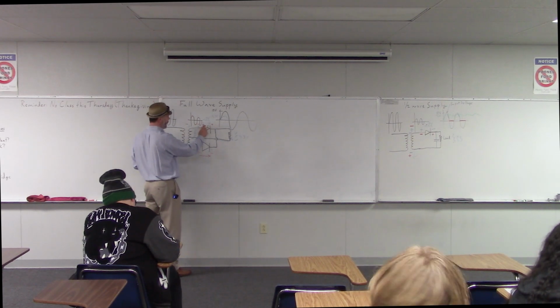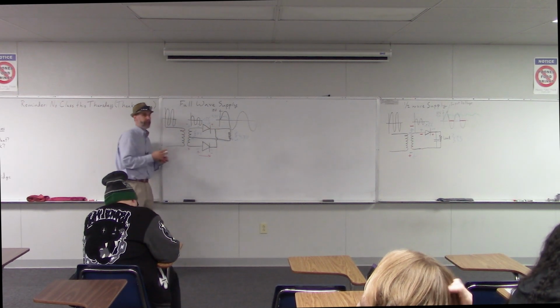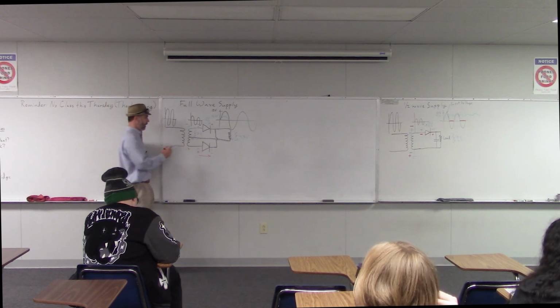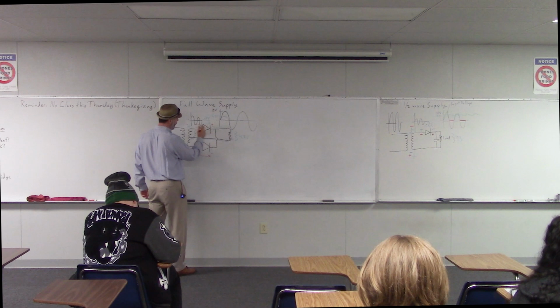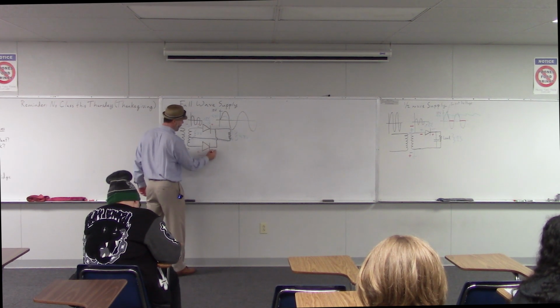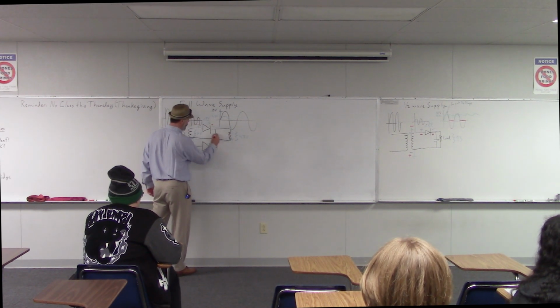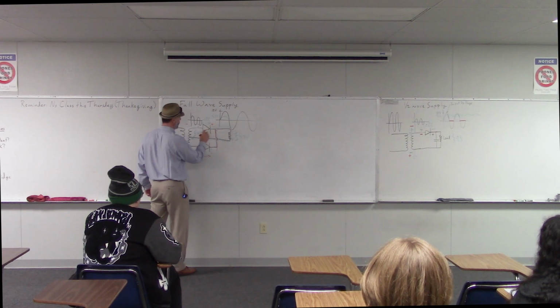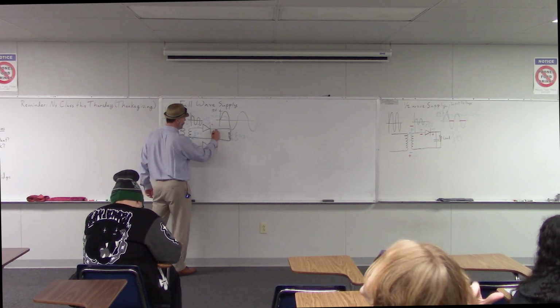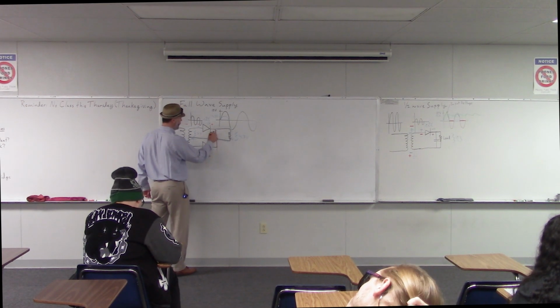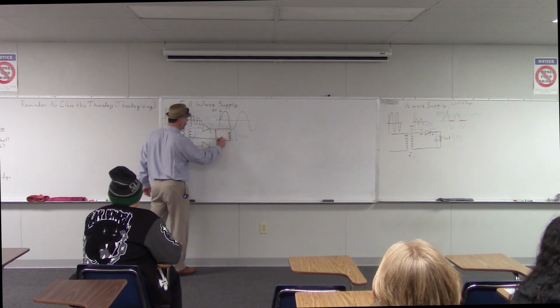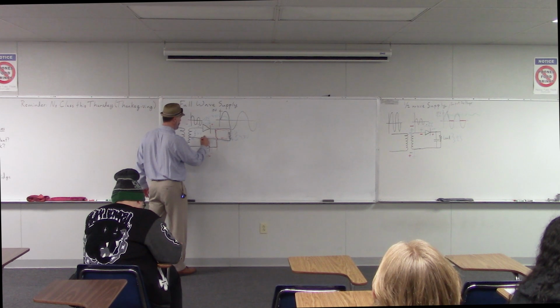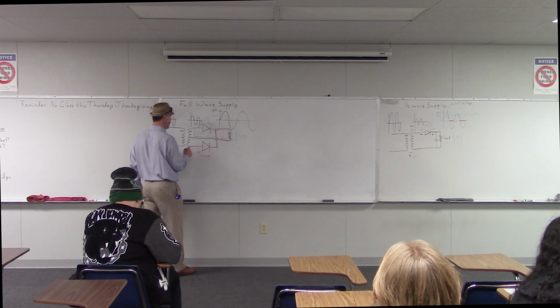What about this top diode? Is that one forward or reversed? Reversed. Okay, so the electricity flows through this bottom diode. It can't go through the top one because the diode is reverse biased. So the electricity has to find a different way. The only other way it can go is through this load. So it goes there, and then again, it comes back to the middle.